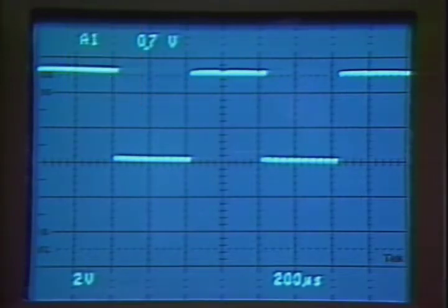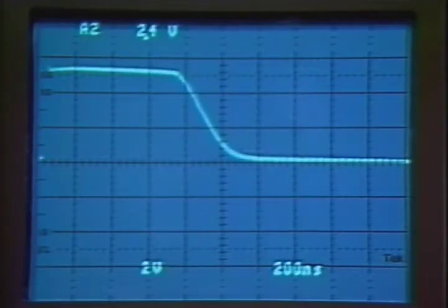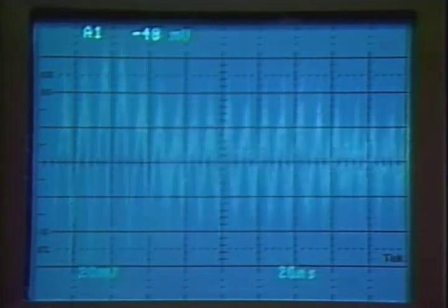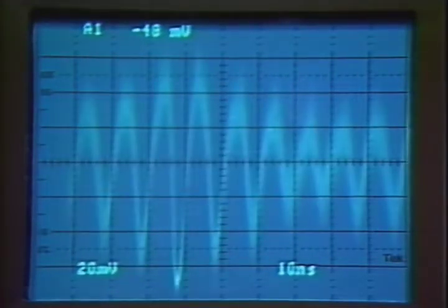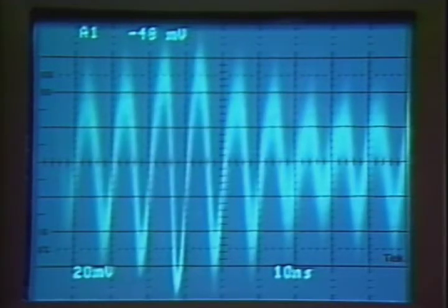For regular, repetitive waveforms, even narrow pulses of low-duty cycle, the scope will present the waveform at 2 to 4 divisions amplitude and 2 to 4 divisions horizontal width. The scope will even adjust the position controls to place the waveform on the screen. It's not a genius. If the signal is noisy or in an irregular pattern, it can't know what you want to see. But for most waveforms, it will present a display that will get you started.